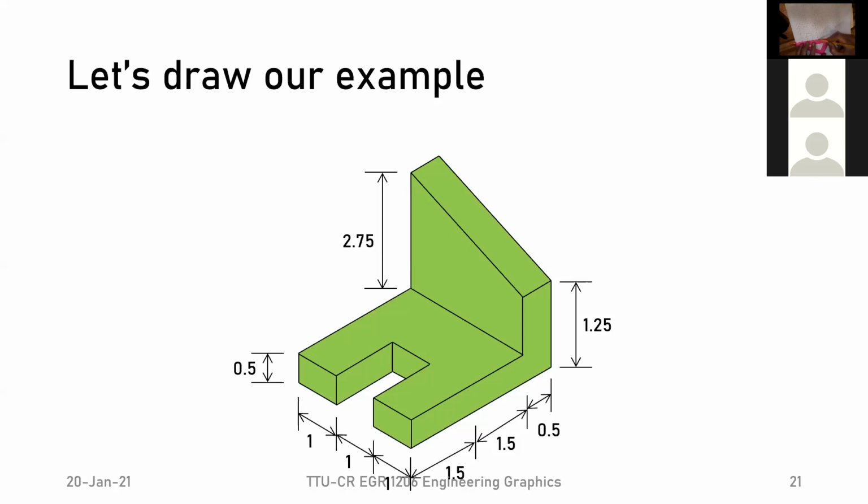Now, if we want to start drawing, right, then we can start with any of these edges here. Again, do it very thin, right? So we can do a nice thin line to extend these points, and so we know they have to go down in this direction. So again, we do a thin line, and now we know that this part right here would be the edge on the front. So it has to have the same height as we get down there, right? So we know we have a point here, and of course it has to have the same height. So we can do a straight line there.